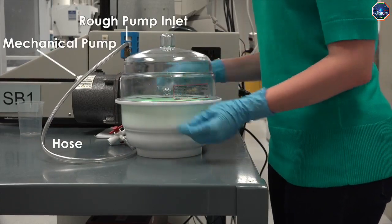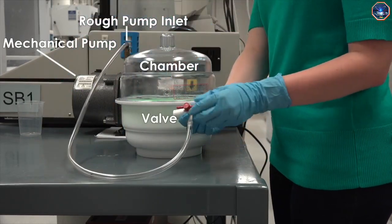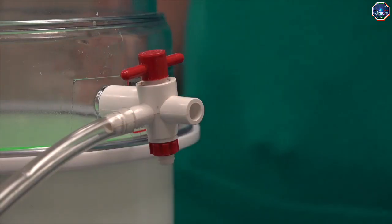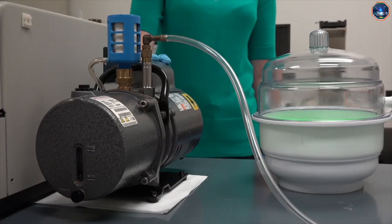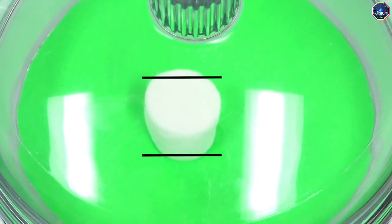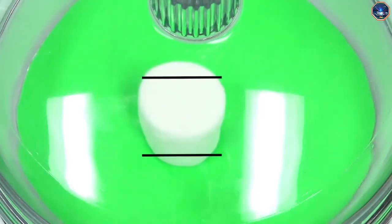First, let's connect the input of the mechanical pump to a small vacuum chamber. Next, let's turn on the pump and proceed to evacuate the chamber. The mechanical pump is pretty noisy. As the chamber pressure drops, we can see the marshmallow expanding. Remember, the mechanical pump is what we call a rough pump. It will only evacuate the chamber to a few torr, or remove about 99.9% of the air. So in addition to the rough pump, we would need a high vacuum pump to achieve lower pressures. But the mechanical pump is sufficient for this demonstration.